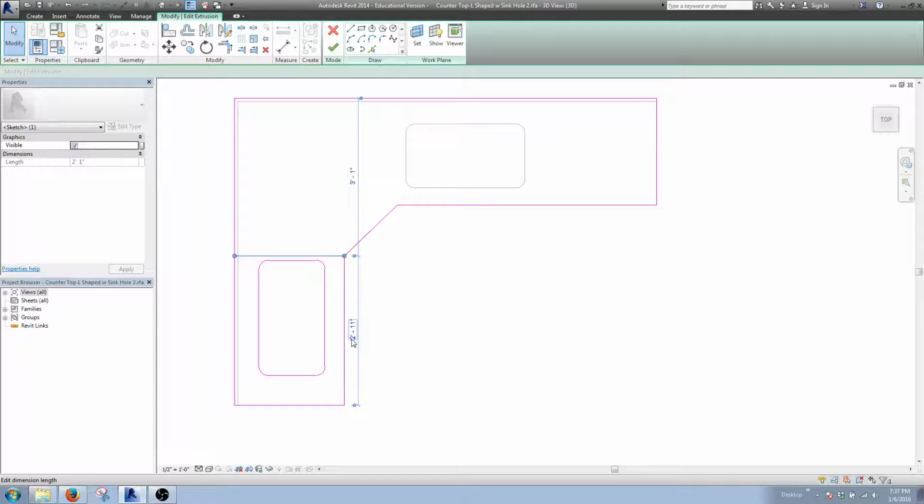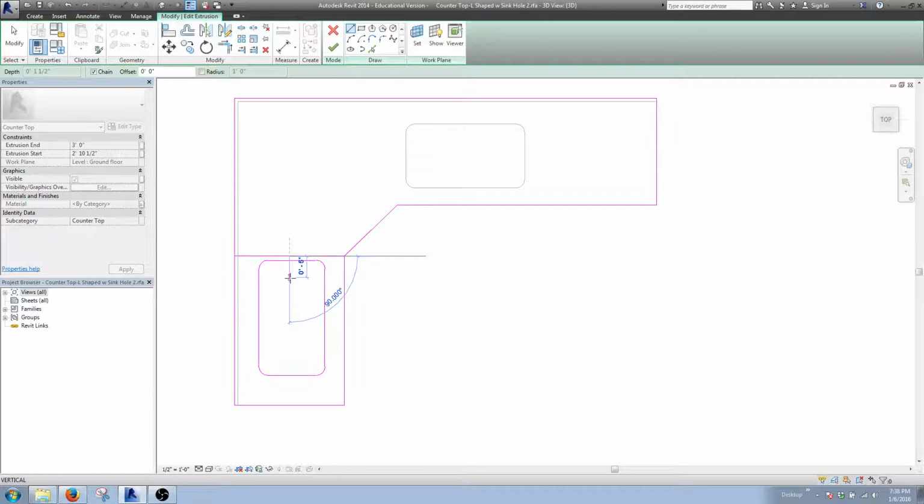What you don't see here is I'm going to pull out my construction calculator once I dig it out from underneath all these things. And I'm just going to punch in 2 feet 11 inches divided by 2 because I'm lazy. And we realize that the midpoint is 1 foot 5.5 inches. So I know this. All I'm going to do is take this line, midpoint, down until I get to 1 foot 5.5 inches. And then we got that. So that's the midpoint between these two guys.